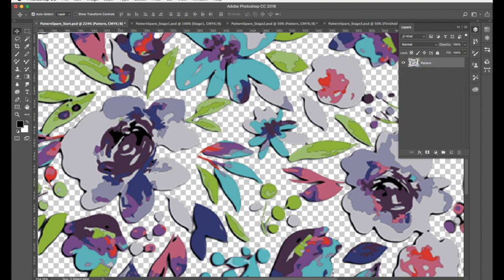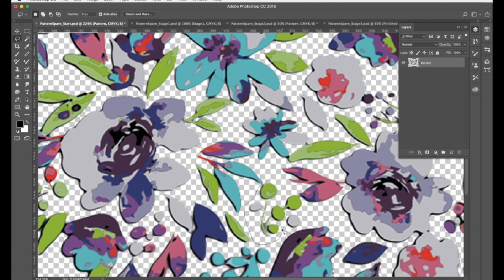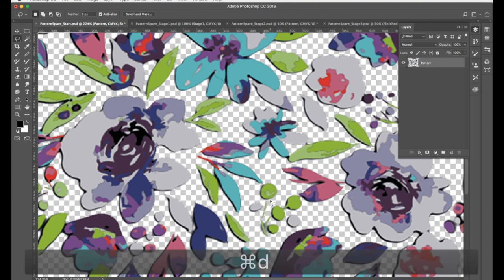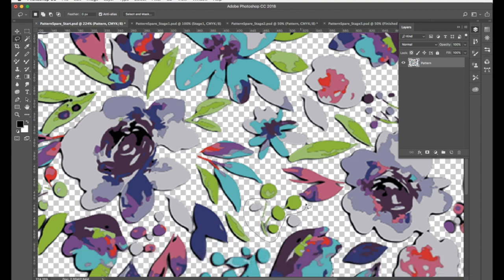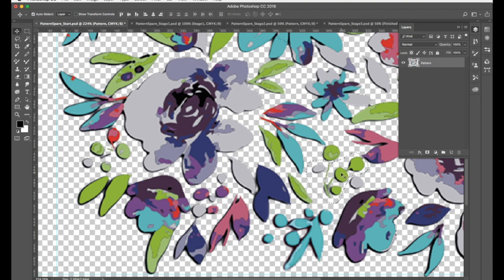I prefer to, with my lasso tool, I just typed an L there, shortcut, I'm going to just pinch a bit of artwork that I want to duplicate, marquee around it. Actually I'll just take these little blobs here, and this time when I change to the move tool, V, I'm going to use an alt drag method of duplicating. I'm just scrolling around on my artboard, holding down the alt key over a selected set of pixels gives you a double-headed arrow in your cursor, a black and white arrowhead instead of the standard black arrow with scissors underneath. It's a great way to very quickly select and duplicate image elements.